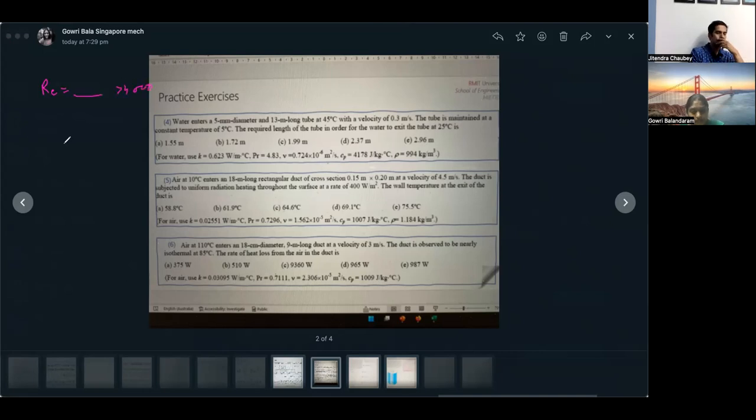Then I found the Nusselt number, by using the 0.023 equation. And it's for cooling, so I use n equal to 0.3. Yes, cooling, correct. And then I used the formula to find h. h was calculated using Nu equals hD over k. I got 11.1763. And then after that, I tried to use Q equals h A s delta T log mean, but that's where I got a bit confused.